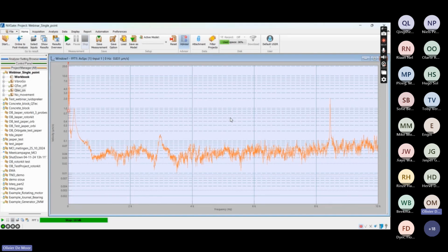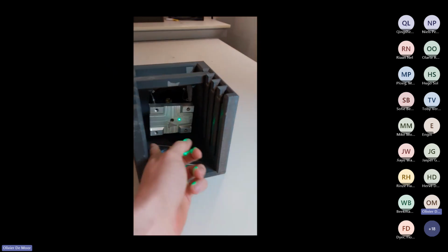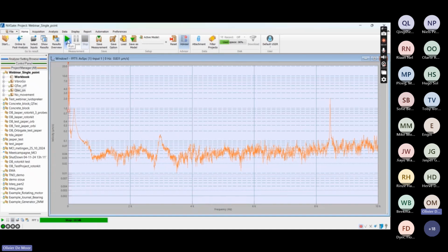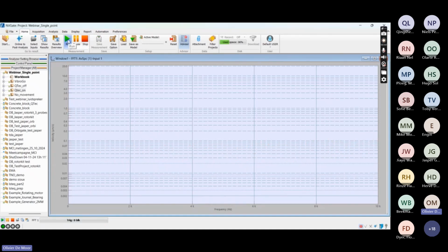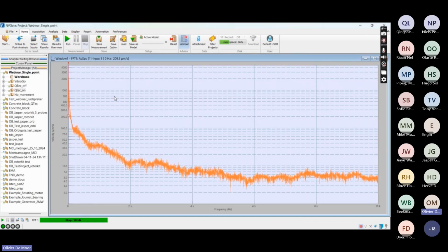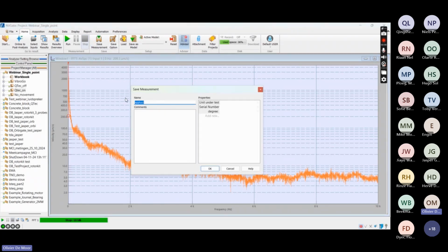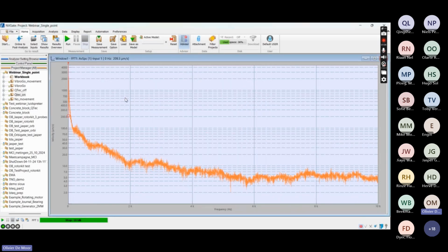Now we will do the same measurement again, but we will make the plate swing again while doing this measurement, so that you have again the large displacement moving in plane direction and out of plane direction. And now we see with the helium-neon laser that you don't even see the vibration peak, so you don't even see the resonance peak because it's just in the noise floor of the measurement itself. So we also save this so we can compare it to the previous measurements, and we can make a comparison of all the different results.